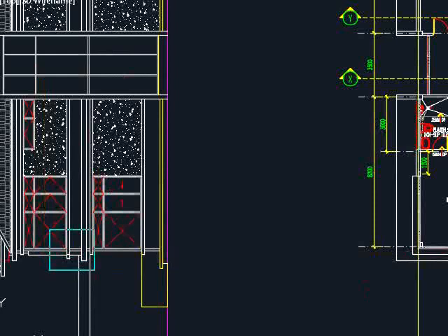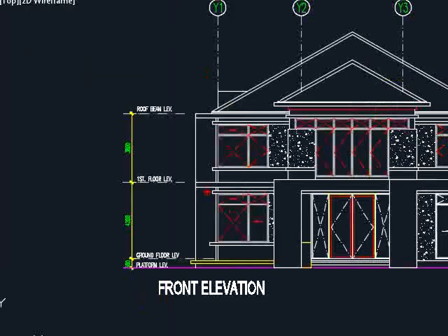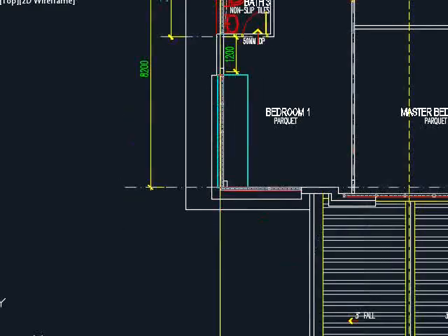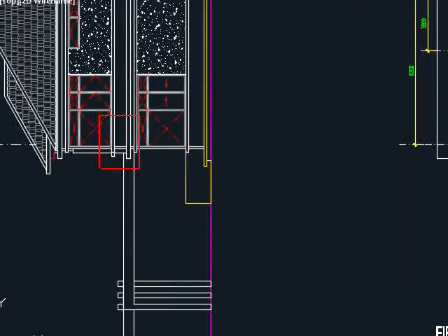If you find difficulty to imagine this, you might need to look at it in the front view. This is a part of the architectural design, which later when you design the beam, you need to ensure this part and this part are attached to your beam. That means the perimeter beam here, which is referring to this part and this part, there will be a special design. It shouldn't be a typical square or rectangular section. It needs to come together with the architectural element.